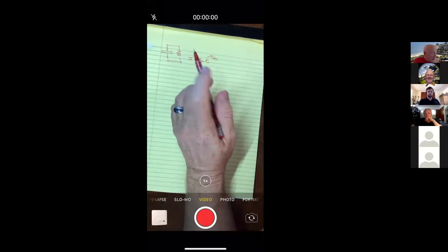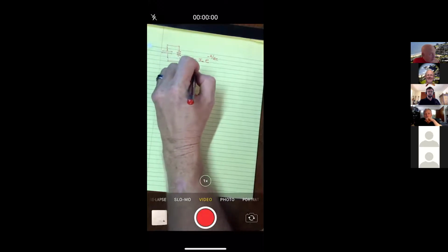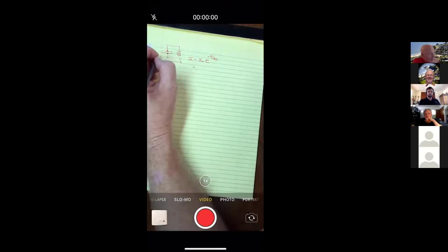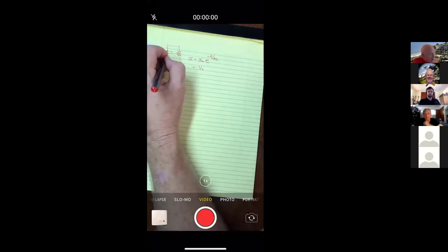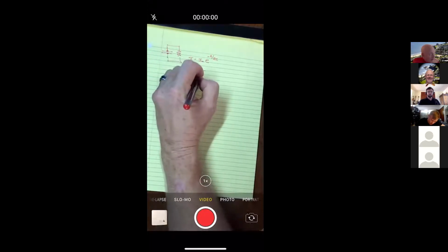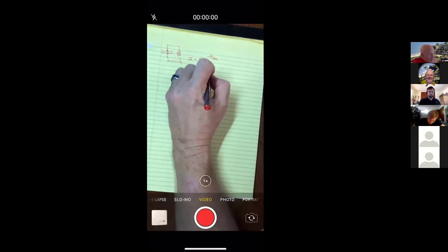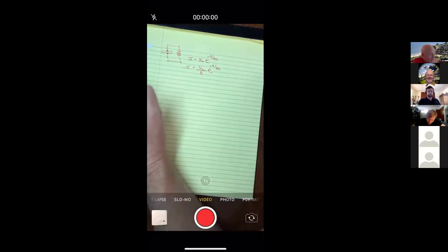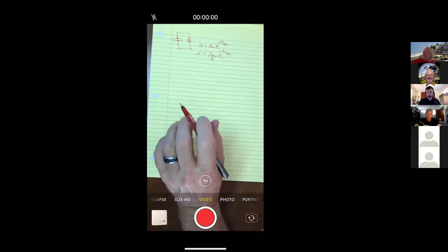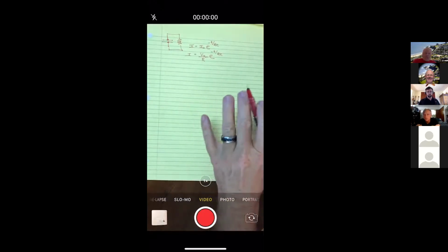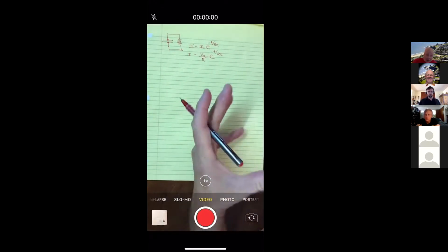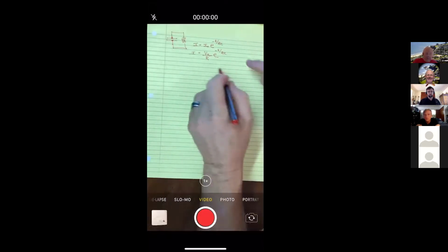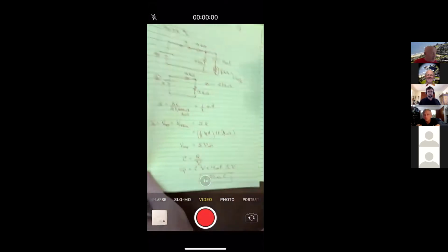Let me go one more step. This initial current was actually the initial voltage on this capacitor divided by the resistance you're driving it through, and then it decays. We solved a little differential equation to get there. If you like, I can solve it for you again. I'll do it after the problem, because I would suggest for this problem you remember that, because that's exactly what is going on here.